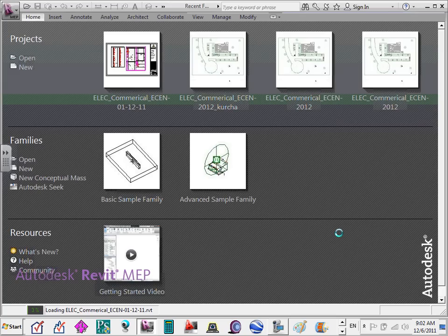Cool? Can I get you guys to listen to your friend Chad? Mine has a different one. It's got the Detach from Central and it's got the Create Local checkbox. Yes, because yes. No, yes. Mine has the option to click both of them. You want to see if Create a Local File is clicked for you. That's okay. You want to create, so leave it as is, basically. It should be Detach from Central not clicked, Create Local File checked.